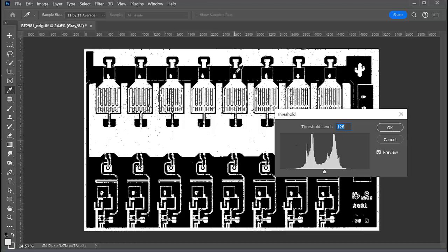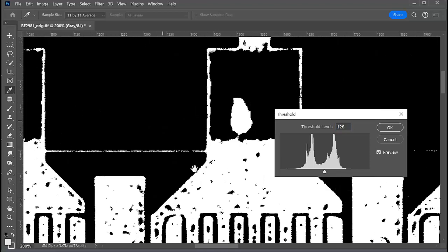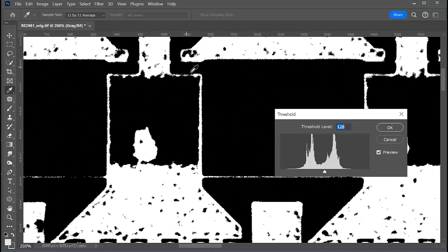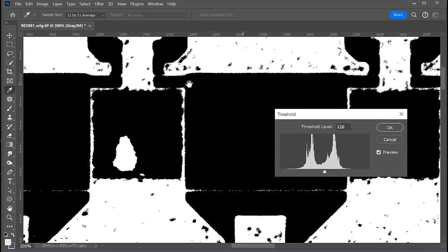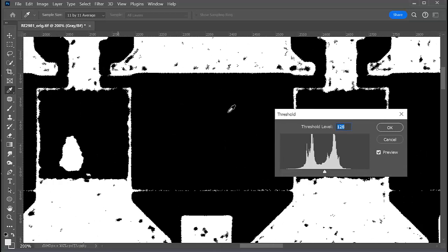Now what I have to do is examine these die pads to make sure there's no short circuits between the die pad itself and the rest of the layout. That'll prevent me from identifying these die pads based on their size and shape. So let's zoom in. We can see right here there's potentially a couple of shorts. And if we continue looking at a different die, we'll see there's areas where there's shorts. That means the threshold we've picked is not the best one. We need to modify it a little.